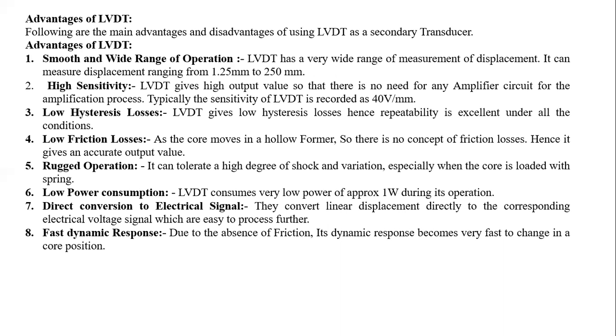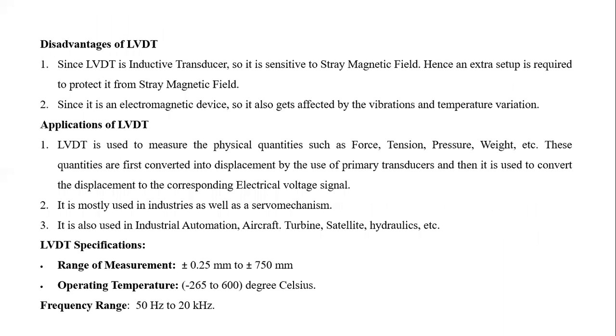The linear displacement is directly converted into a corresponding electrical voltage signal. The last one is high dynamic response. Due to the absence of friction and dynamic friction losses, its dynamic response becomes very fast to changes in the core position.